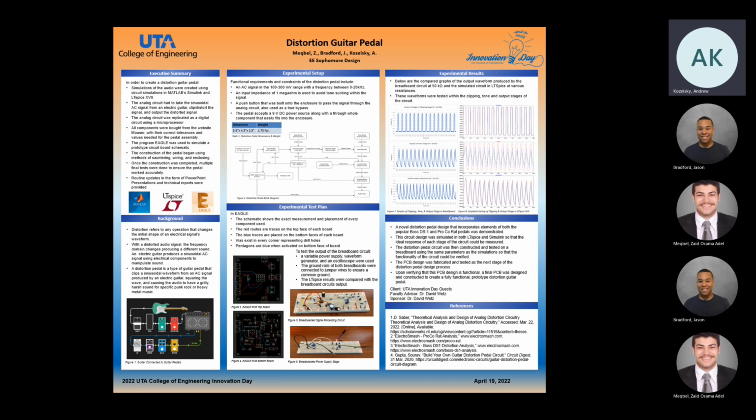Finally, what you can see is the output of the whole circuit being measured at the very end of the output, essentially what you would see at the end of the audio jack. For that stage, what we tested in LTSpice was the tone and the level potentiometers both set at about 50%. Then the distortion potentiometer was varied from 0 to about 50% to full distortion.